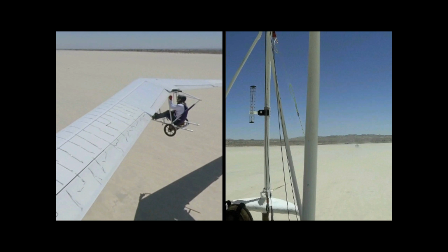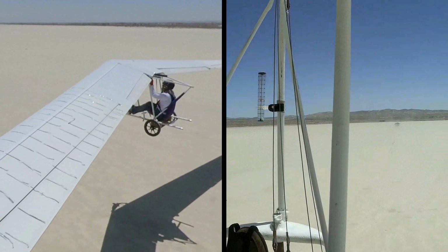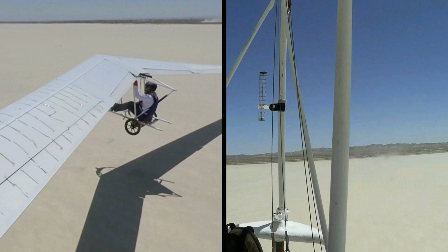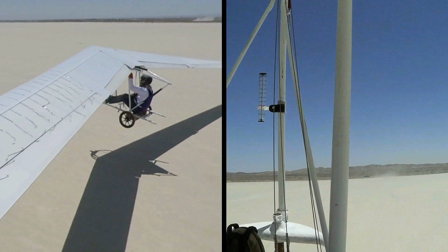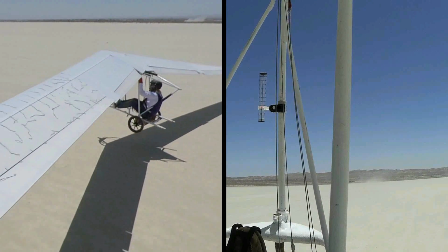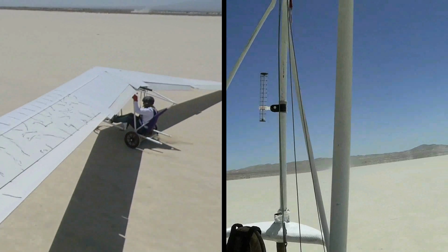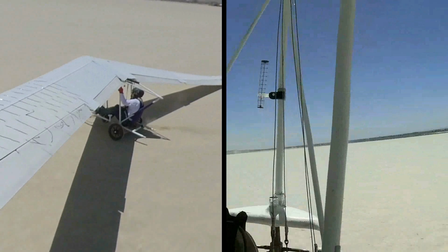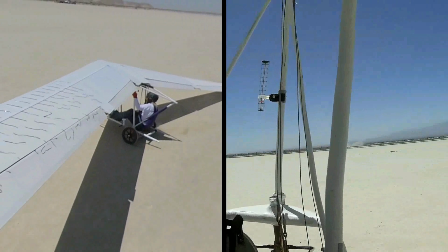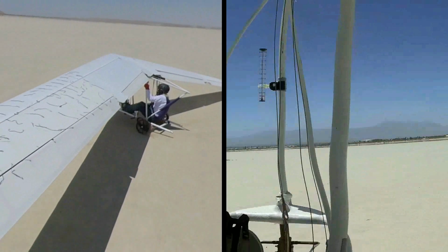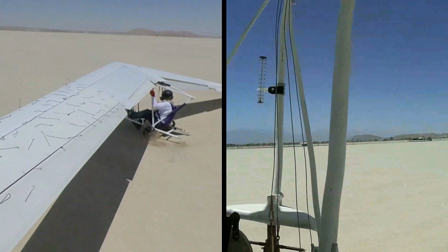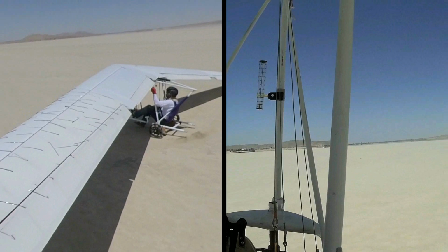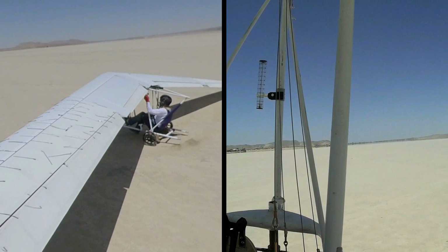Okay, so keep your eye on the airspeed and the elevon there. It's up to neutral, flow's attached. I'm putting the nose back down again, back up, reattaches. Oh, starting to separate. Airspeed's down to 20, which is stall, and out of the sky I fall. So a very tricky situation that's hard to control because of the non-linear performance of the control surfaces. You just can't keep up with those changes. And this is probably the only time you'll ever see a flying wing ground loop. One of the wheels came off a rim and I went sliding around the lake bed.